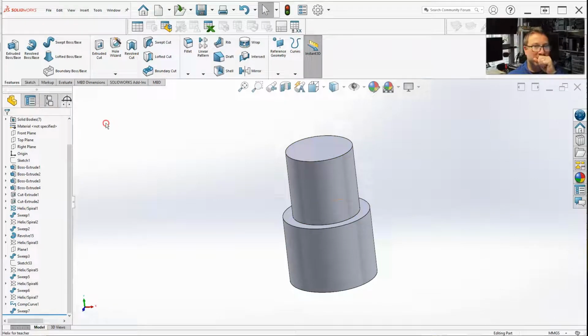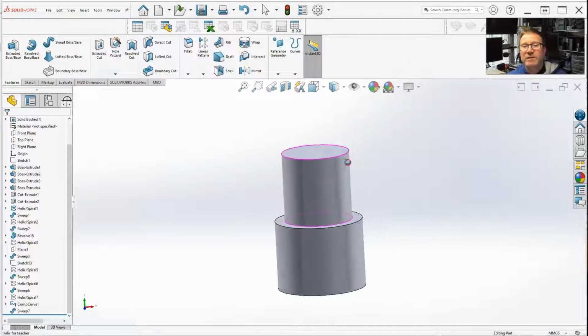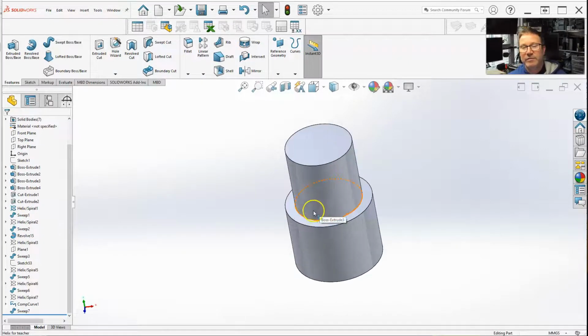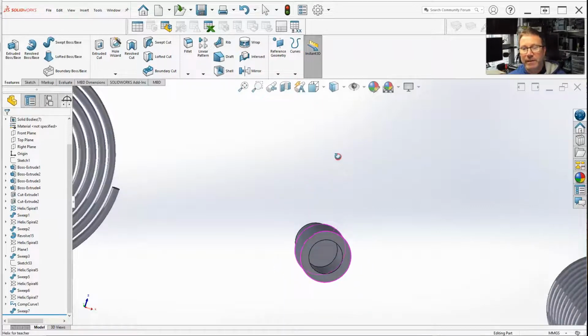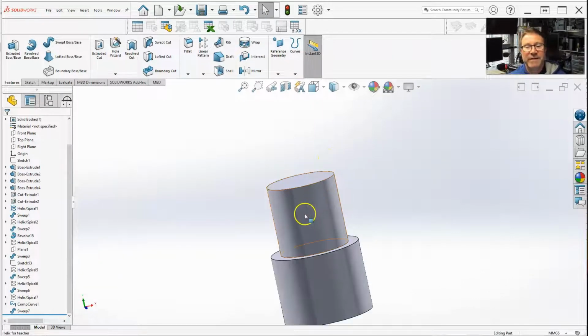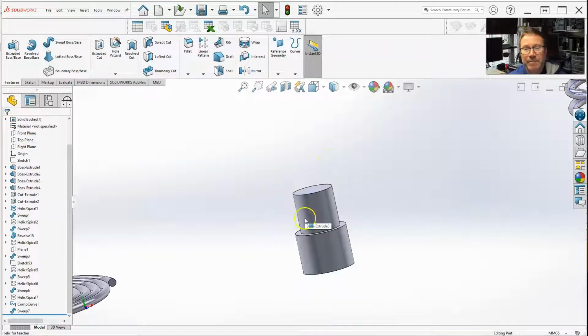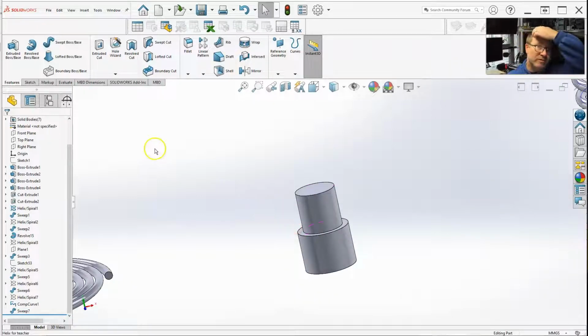So the one thing we can do, I actually constructed this little double cylinder, one with the inside cut out on one side and then extruded on the other side for basically M20. One thing you'll notice when you're using the actual tool is the Hole Wizard thread. But when you're using regular standard threads, it's much better, if you're doing external threads like on the outside of a bolt, to pick the major diameter of the actual bolt.